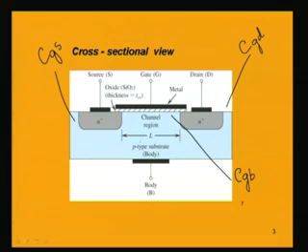Because this body is made of P, we are considering a MOSFET device having a P type substrate, so it is an N channel MOSFET. In between the source and the body, meaning the substrate, we have a p-n junction. Similarly, the drain has a p-n junction between the substrate and itself. So, there are two p-n junctions.